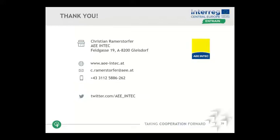However, if you have a setup without oil and gas boilers, what people do is that they include emergency connection points so that they can use mobile heating devices in case of an emergency. I suggest to consider that anyway, even if you have an oil or gas boiler, in case of a large breakdown, a large emergency, which we had to face in Austria as well, one or another time. It's very important to have such connection points outside of the heating plant so that you connect a mobile device. And as an operator, you should be aware of where you can order or where you can get such a device and what time you need to get such a device.